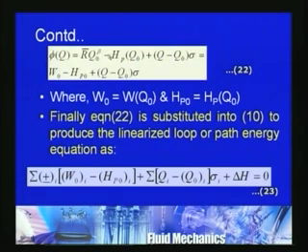So, here you can see that this beta is generally used as 2. So, we finally get equation 22 as a linear equation, and after substituting it into our earlier energy equation 10, we get equation 23, which is the general form of the equation which we can utilize for the solution of pipe flow networks.